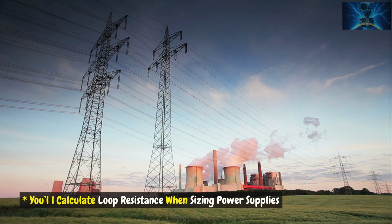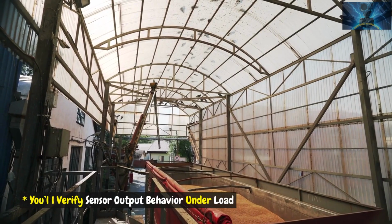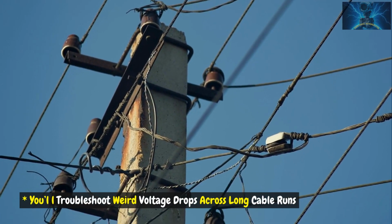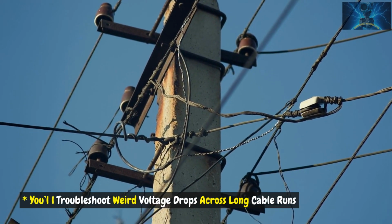Why this matters in instrumentation. You'll calculate loop resistance when sizing power supplies. You'll verify sensor output behavior under load. You'll troubleshoot weird voltage drops across long cable runs.